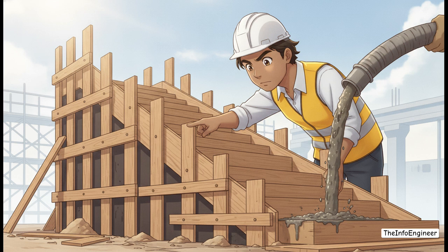Furthermore, staircases are notoriously difficult to cast. You must add appropriate wastage factors, especially if the design calls for complex sliding, climbing, or highly detailed stepped formwork. And speaking of formwork, remember that the standard method of measuring dictates that the sloping soffits, the vertical risers, and the outer edges must all be measured and priced as completely separate formwork items.